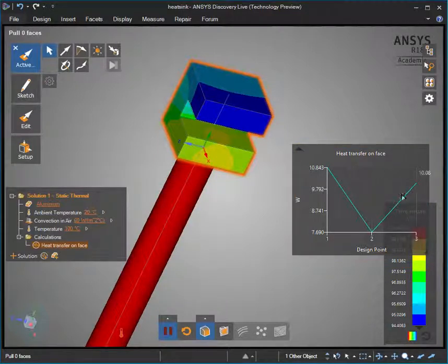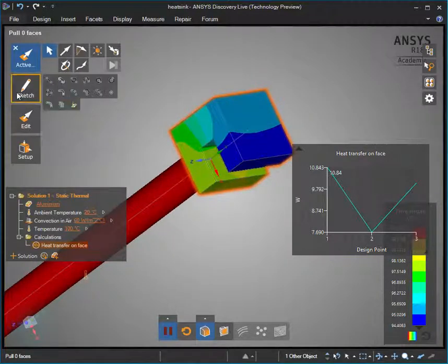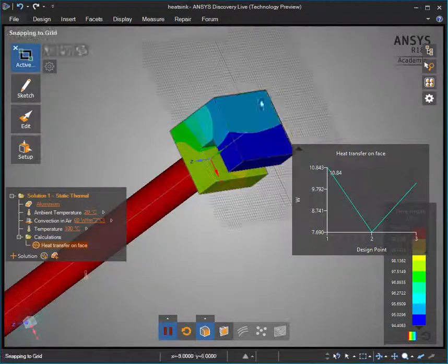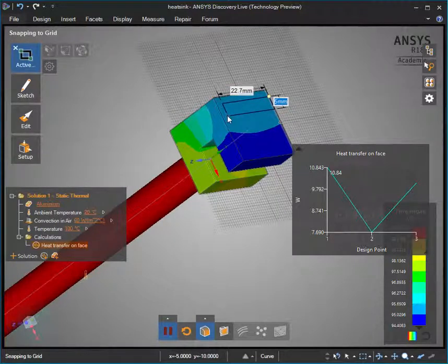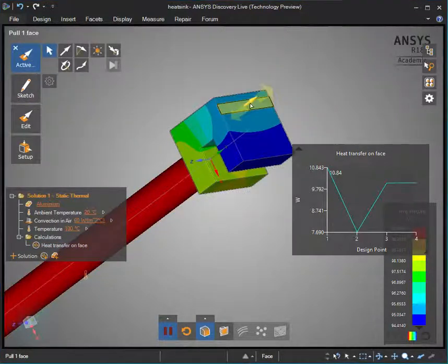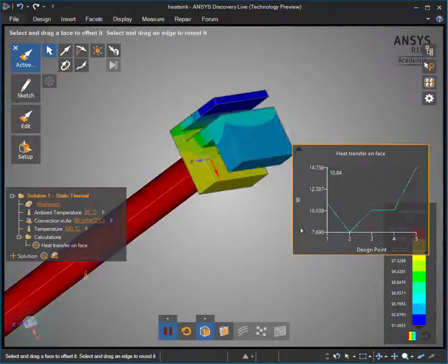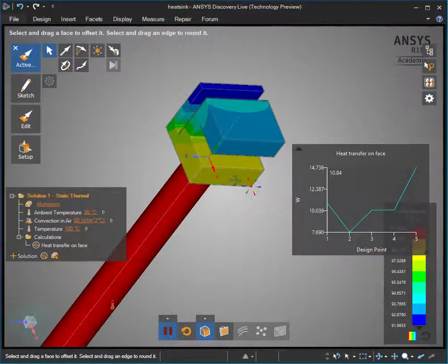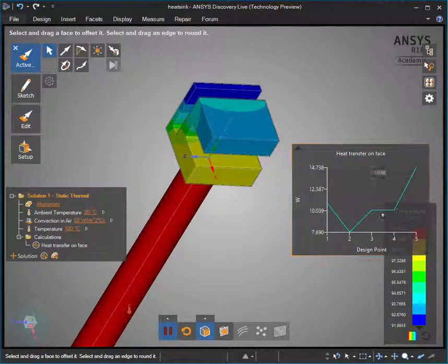And we see this time it did the exact opposite. So increasing the surface area of our heatsink here in any direction made the design more efficient. We're way up here in the positive values, so many watts of energy. I'm going to make a valley on the top of this as well, just to show that we would expect this to also increase the heat flow because we'll be increasing the surface area. And that again made a large jump up there in the efficiency, so that's good. Almost doubled what we had before. Oh, not nearly, up by a half at least.